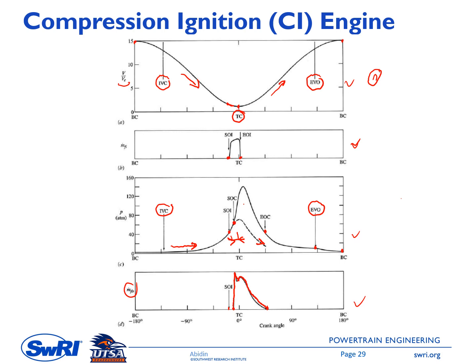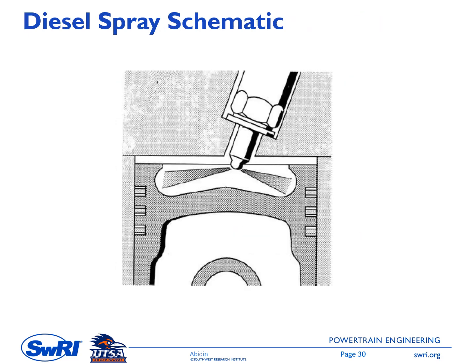So we'll learn about this profile in more detail in chapter 10. This schematic is showing the diesel spray. It has one injector here, and this injector might have 2, 4, maybe 7, 8, 12, 16 holes. So one injector can have 2, 4, up to 16 holes. We have done research up to 16 holes for one injector.